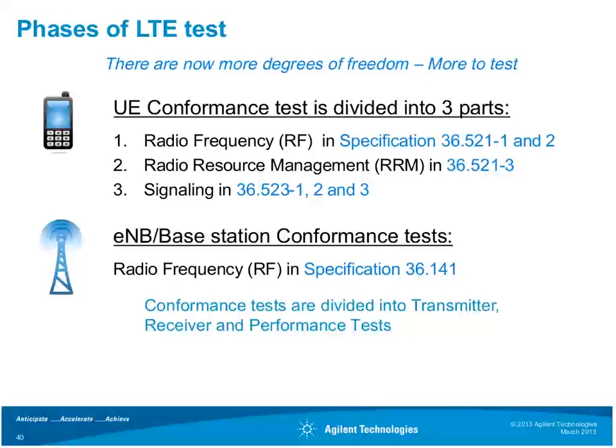First off, there are more degrees of freedom with LTE than any previous radio standard. And this has a direct impact on the number of tests that can be carried out. We have 28 frequency bands. We have 6 different channel bandwidths. There are multiple modulation formats, multiple MIMO configurations, and a lot of interoperability that has to be tested. All of these need to be considered in the conformance standards.